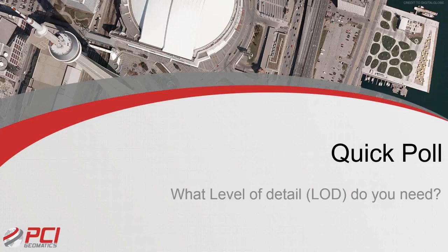Yeah, absolutely. The Z values are definitely moved over and collected and stored in the database that is exported out. There are different formats that we showed: KMZ, shapefile, Collada, etc. All of those formats basically assume that you're going to be doing something with the data that is 3D. So definitely the attribute information is transferred along. Some things that I didn't show were, you can definitely drop points like street lights.